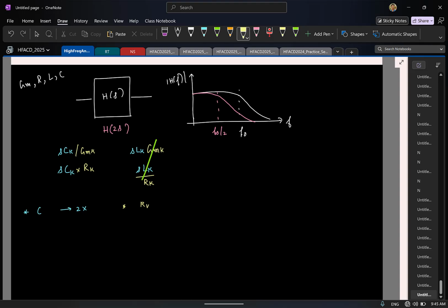I can make Rk to be scaled and gmk to be scaled. Let's ignore inductors. You can do either of them, but of course each of them will have its own pros and cons. So let's just see what will happen in both cases. Tell me, if I only scale the capacitors in the circuit, what can you say about the low frequency power spectral density?